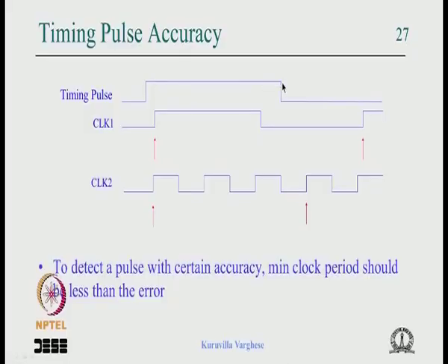There we said that the write to the FIFO should be of certain width, and we decided to put a counter outside, and the counter will count from 0 to some particular count, and we will decode that count and give it back to the state machine. And the state machine will detect that change when it reaches that count and stop that write pulse, that was the idea. So we are in a similar situation, I am showing in the picture.